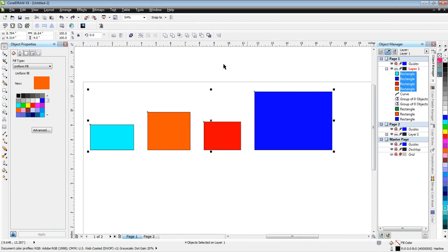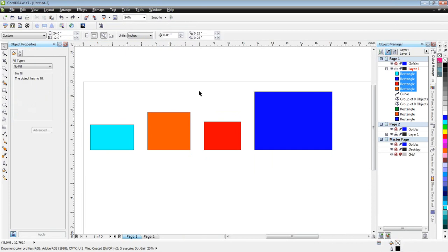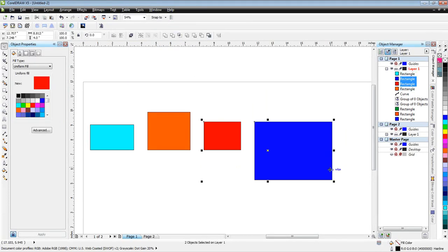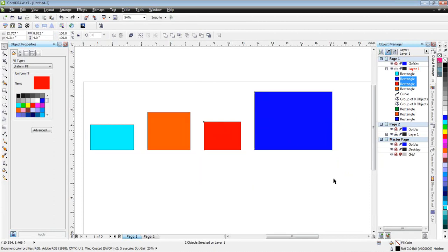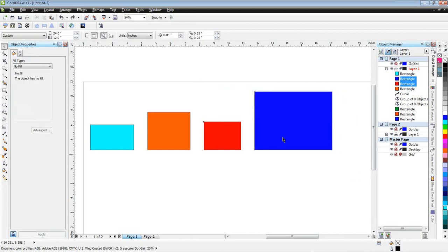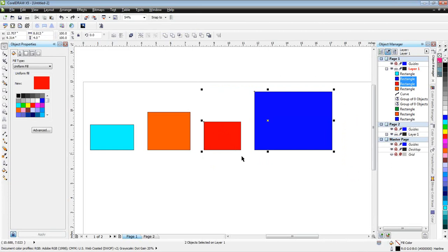to work with. So say I need these two at the bottom and these two over here at the top. I hit top on that one, and it matters which one you select first. I selected this one first, so the top of that one went to this one. If I had gone the other way in my selection and hit top, oops, sorry, this way, now it matters in which way you select it.